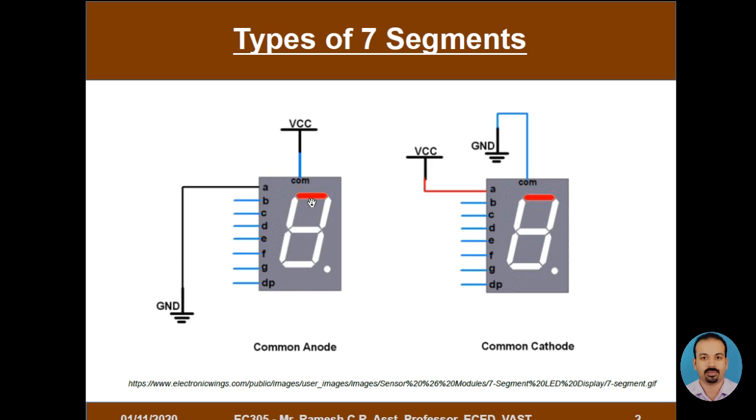Similarly, based upon the type of semiconductor that is used, we may get a 7 segment display where on turning on the segment you will get a red color, sometimes it may be blue, sometimes white, etc. You have seen all those things. So based upon the color, again, as we have seen for the LED, we need to use some resistors in between, so that the segment will be protected from high current or high voltage applications. Similarly, the voltage limitations can be handled.